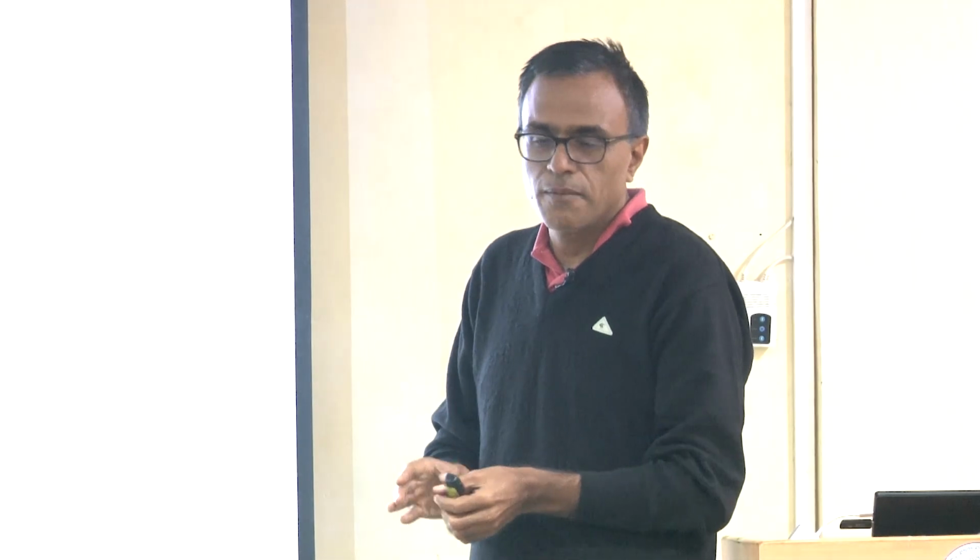So I gave you a bird's eye view of how the channel estimation can be done in time domain, because using these cyclically shifted sequences, you can artificially create time domain channels which are not interfering with each other. So you estimate the channel there, bring them back to frequency domain.